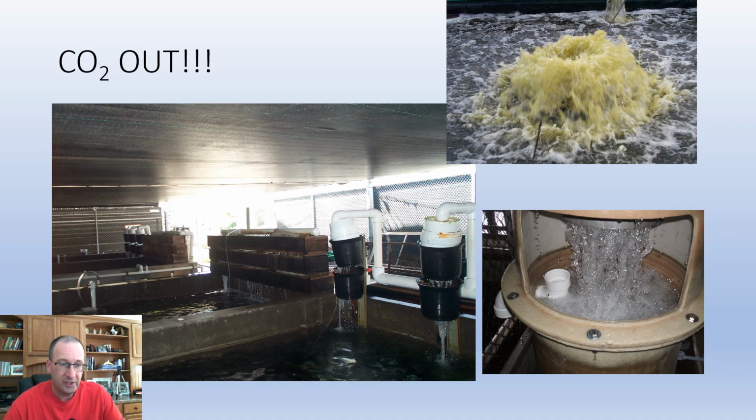The more you bash it around, the more carbon dioxide is able to leave the water, or to degas. And therefore the water going back into the system should contain significantly less CO2 than what was coming through the packed column when you started. Any way that you can do this, whether it involves high-tech or low-tech, works. I always prefer the low-tech, which is kind of in our budget and is pretty easy to replace if something should break. And all it takes is making the water rain down through a couple of air stones.